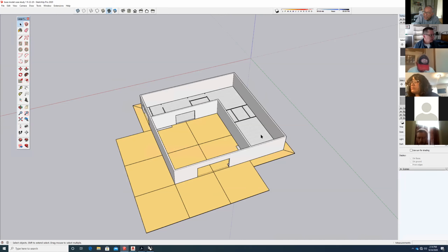How many of you have SketchUp models that are different colors, both blue and white? You can just raise your hands. I can't see all of you, but mine was. So what I did was I went to the walls and triple-clicked them. I went to Colors, Named, and I picked snow.